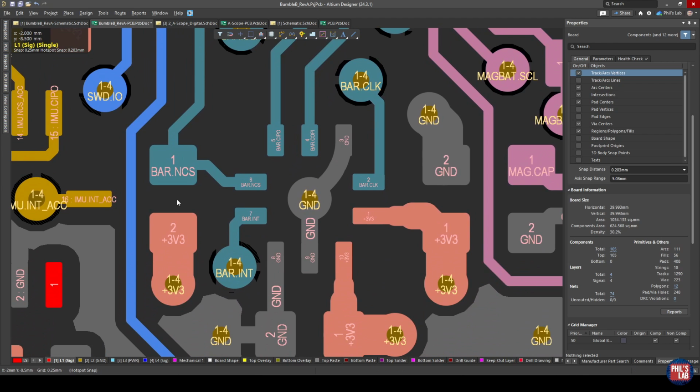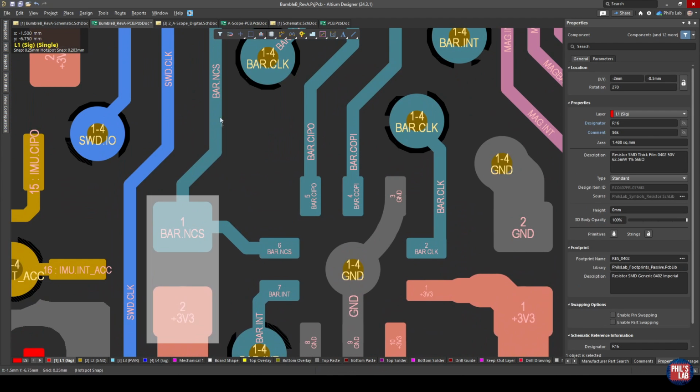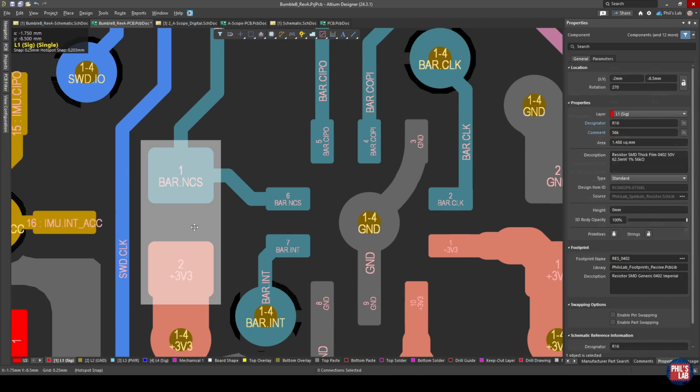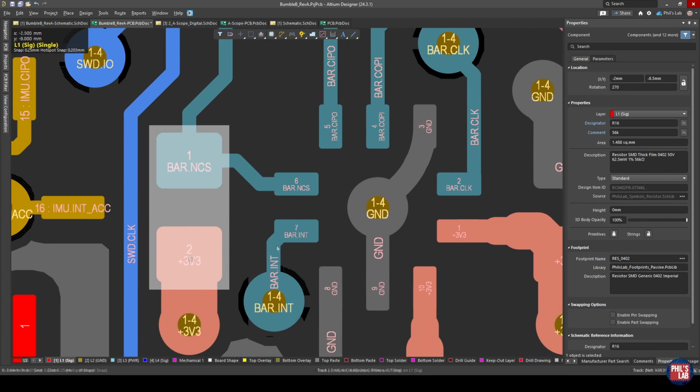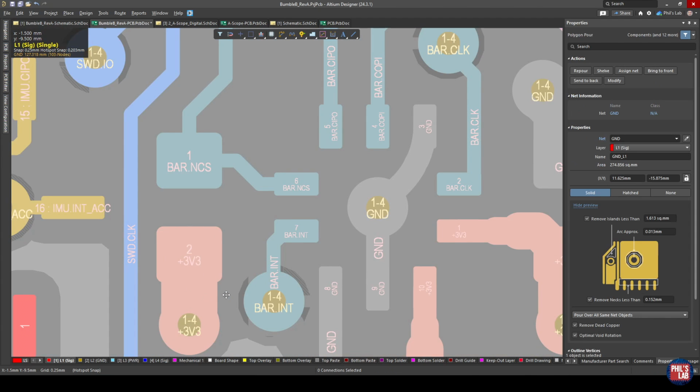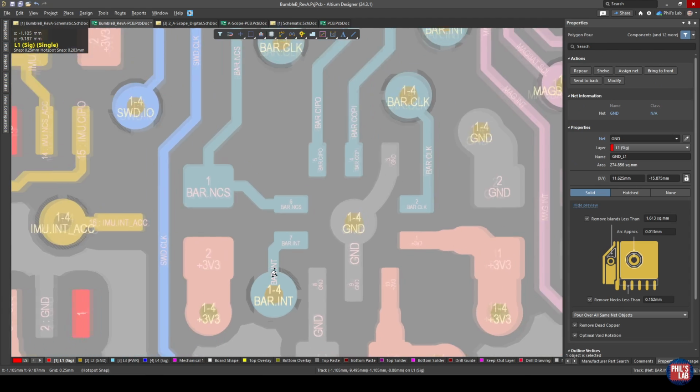And the pull-up resistors, for example, for the chip select line, I'm routing in to the pull-up resistor, out of the pull-up resistor into the chip select line. The pull-up resistor is placed close to the peripheral, and the other side of the pull-up resistor is pulled up with a wide trace to my I/O level voltage. There isn't really much more to that.